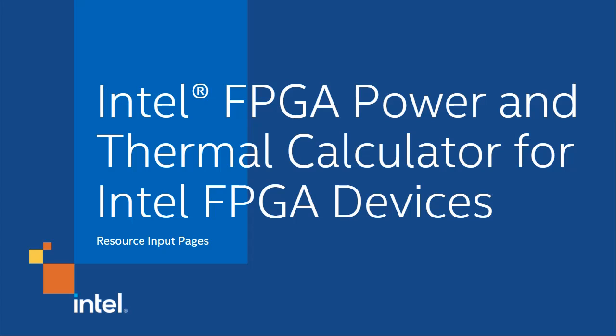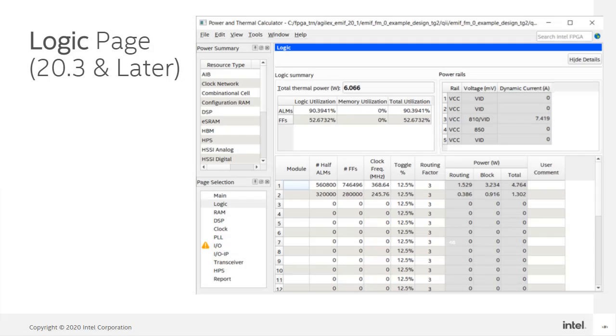Now let's take a brief look at each of the pages in the PTC and some key inputs that should be provided to get the most accurate power analysis. Let's start with the logic page. Like the main page, information is entered into the white or light gray cells. On this tab, each row represents a design module, allowing for a breakdown of resource usage and toggle rate for each part of the design.